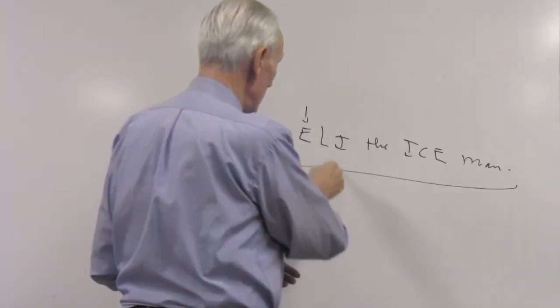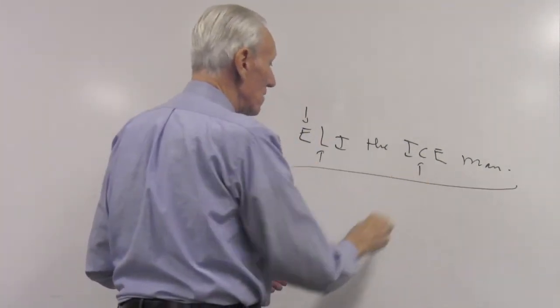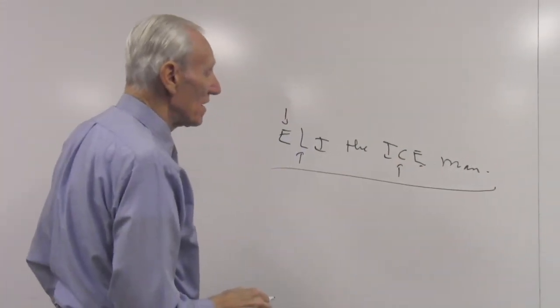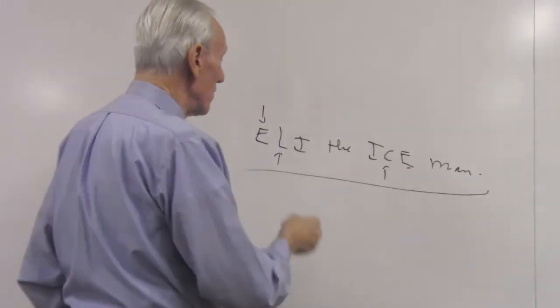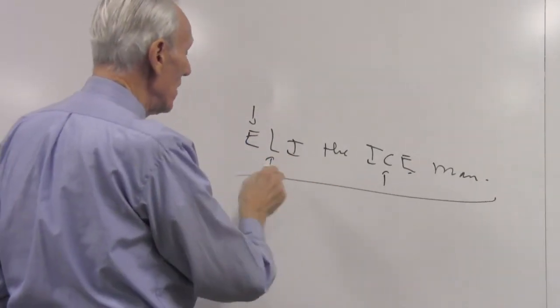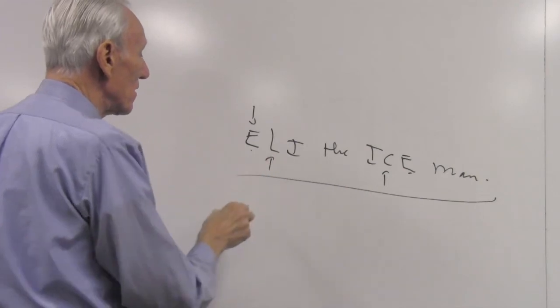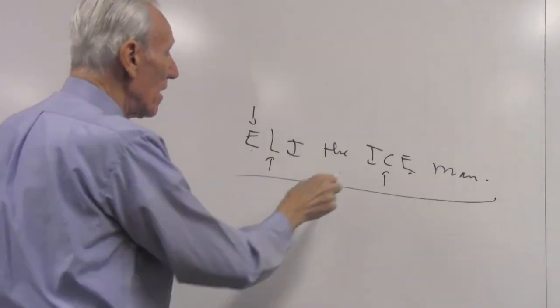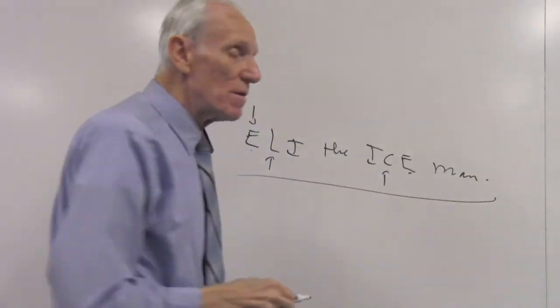That's the inductor there; there's a capacitor there. So the current is before the voltage in a capacitor by 90 degrees. That's how I know which way to draw the diagram, whether the current or the voltage is in front. Voltage precedes the current by 90 degrees in an inductor, and the current precedes the voltage by 90 degrees in a capacitor.